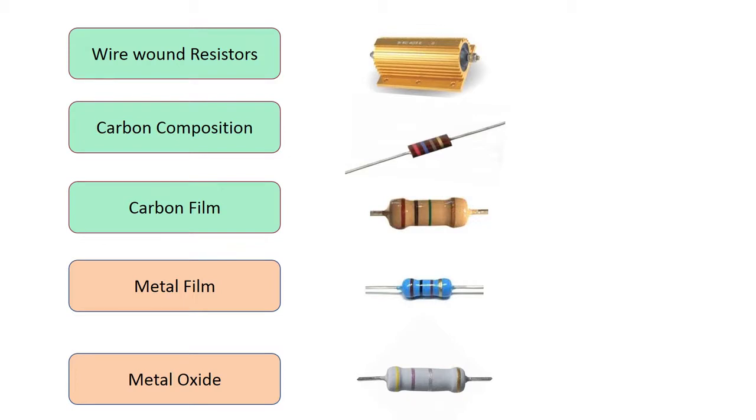They are made out of a non-conducting core with a thin carbon film wound around it. These resistors have a lower tolerance than carbon composition resistors but have inferior properties compared to the metal and metal film resistors. Metal film resistors are similar in construction to the carbon film resistors but have a metal film instead of the carbon film. They have even lower tolerance, lower temperature coefficient and better stability. Metal oxide film resistors have even greater stability, temperature coefficient and reliability than the metal film resistors.